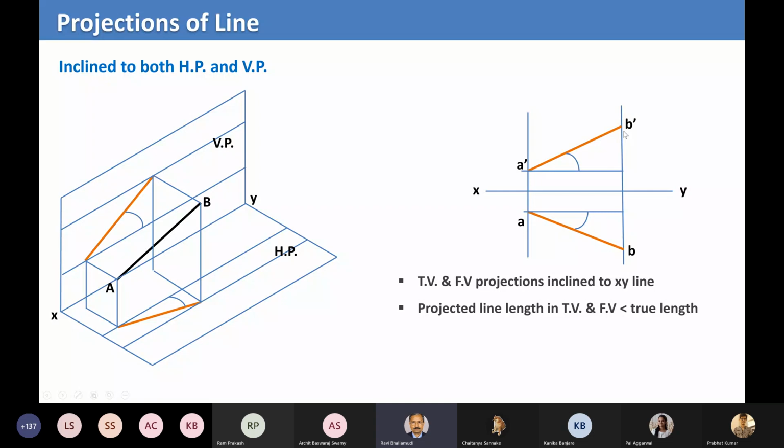And the third input that you may get, when coordinates of both points are not given, is the length of the line being so much. That will be the issue here because you do not know the actual length of the line, which may be more than what you can draw here. So you can only draw a projected line A dash B dash. We'll come to this projection in a minute, but right now just think about drawing the line.